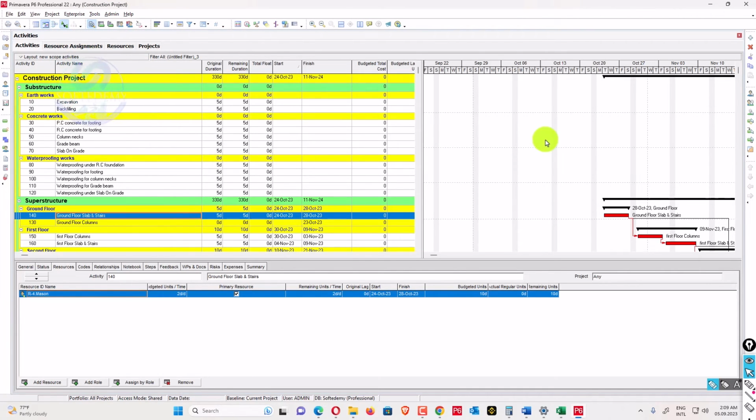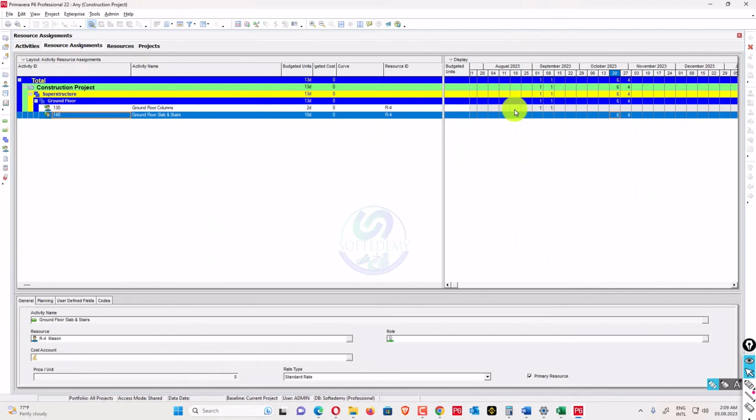But if the project has a 40 or 50 day delay, how can that same resource allocation be implemented? In Primavera P6, in the resource assignment there is no baseline type of budget units. So what will he consider? He will consider remaining early units. He may ask the contractor, please submit remaining early units. He will not even monitor budget units from the updated schedule.